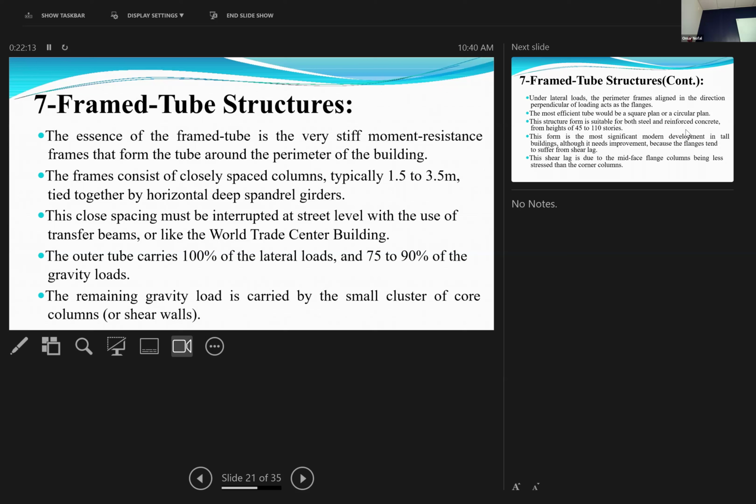When you look at this building at the end, let's say columns here, here, here. When you look at the side view, it's going to be something like this, just like a shear wall, the whole front of the building, and it has some holes for the windows. That's it. So we call it a perforated shear wall, like a shear wall that has a bunch of holes. So somehow we are trying to make the whole perimeter of the building act as a shear wall, a 60-meter shear wall and another 60-meter shear wall. So the whole building is going to act as a shear wall.